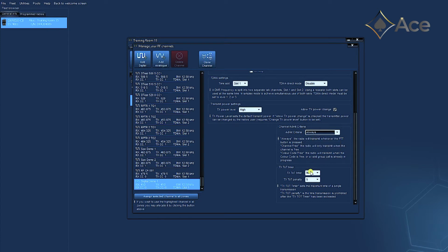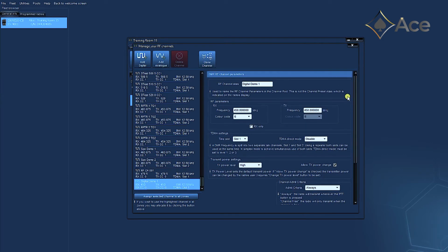Your choice. TX timeout timers. In later versions, this is going to be factory defaulted to 60 and 0. Currently it's at 90 and 5. I suggest you change them to 60 and 0. Once again, that is a personal preference. You can leave it to wherever you want it. That channel is now in my channel pool. I cannot delete that channel, it's there. If I need to reuse that channel, I can reuse that channel without adding another one.